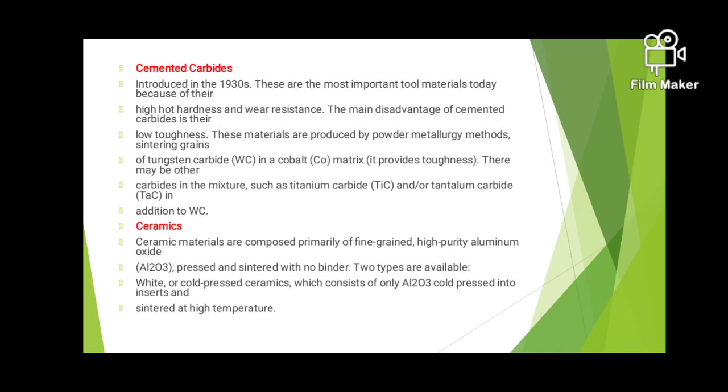So, ceramic materials are composed primarily of fine-grained, high purity aluminum oxide, Al2O3, pressed and sintered with no binder. Two types are available: white or cold pressed ceramic, which consists of only Al2O3 cold pressed into inserts and sintered at high temperature.